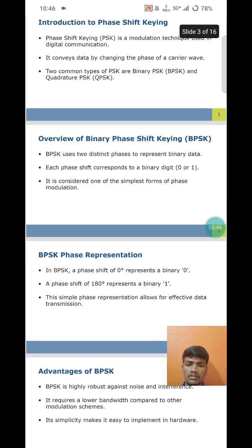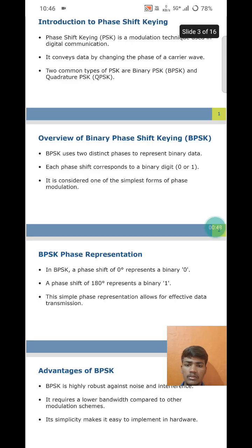Overview of binary phase shift keying. BPSK uses two distinct phases to represent binary data. Each phase shift corresponds to bit digit 0 or 1. It is considered one of the simplest forms of phase modulation.